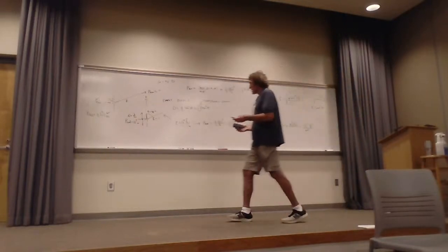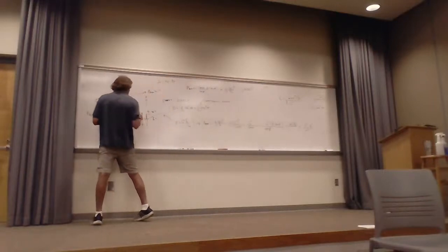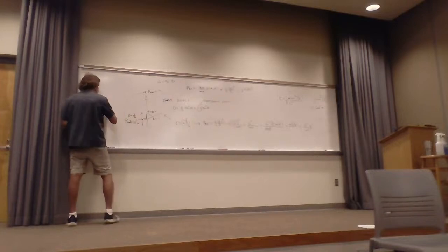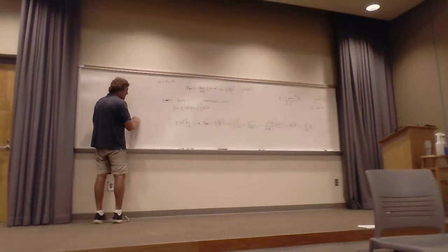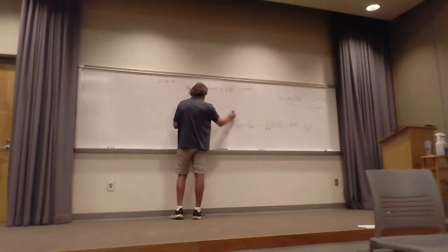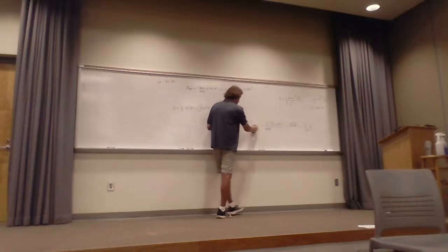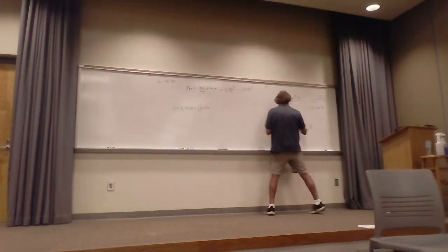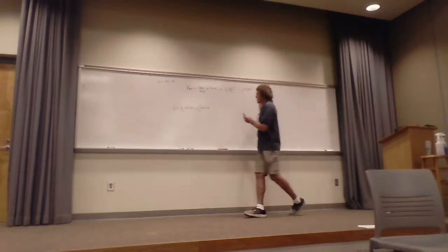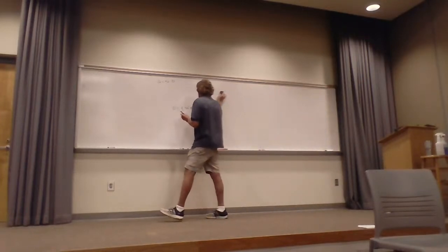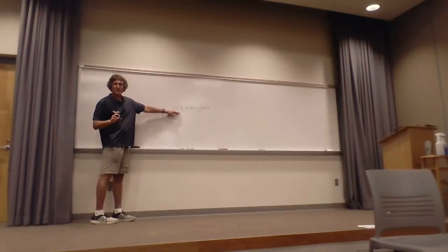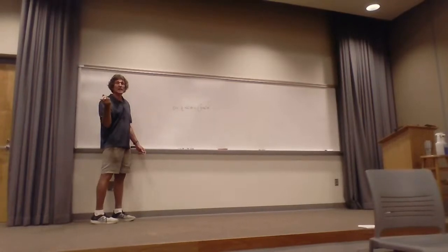Now, I told you that for the short dipole, and this is the thing that's important, the directivity was 3/2 or 1.5 times the sine squared of theta. It's assuming that the antenna itself is at the origin and it's aligned in the z direction. So that's an assumption you have to remember. I'm going to mention something else. I said also that this directivity will hold for all small antennas.